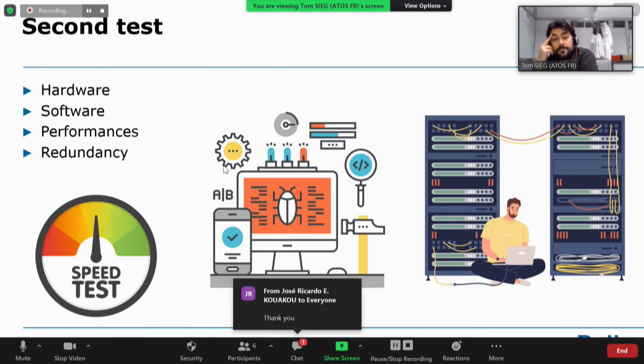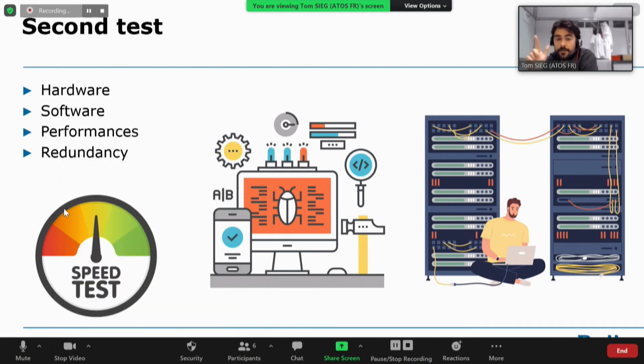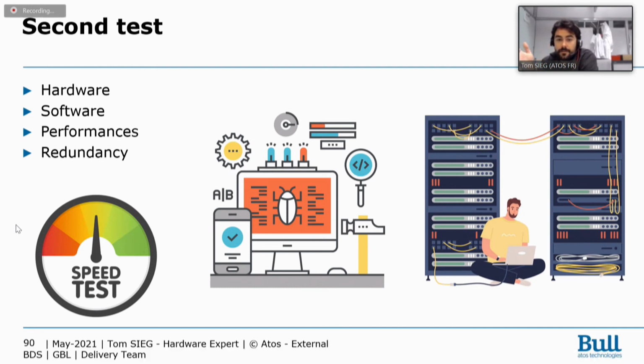For the list of different tools needed for maintenance, generally it is basics: screwdriver, some spare components, that is the basics you need. And after that, it depends on your material. For example, if you have a direct water cooling solution, you will need some tools to be able to dismount pipe, to dismount water connector, to dry them properly before dismounting, to be sure you will not generate a leak into your system, etc. That is for direct cooling parts.